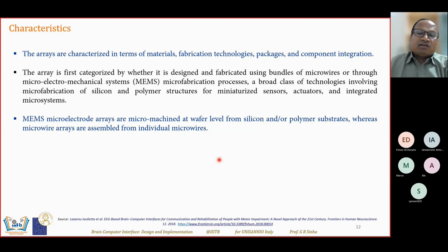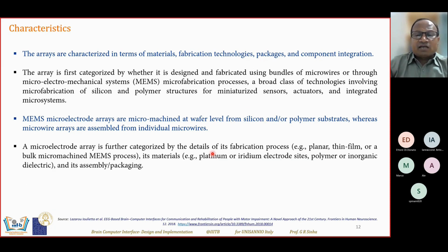Okay, germanium is generally not preferred, and silicon is always preferred at wafer level. It is mainly because of one factor, which is the stability of silicon, which is very, very high as compared to germanium. The stability against variation in temperature and other factors is much better in silicon. Though germanium has higher conductivity and less threshold potential, we use silicon in the wafer. Anyway, let's not go into more electronics details.